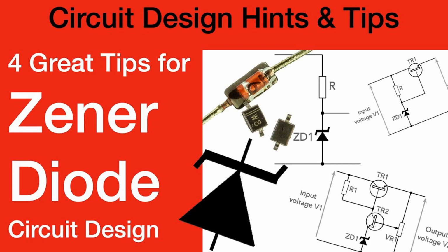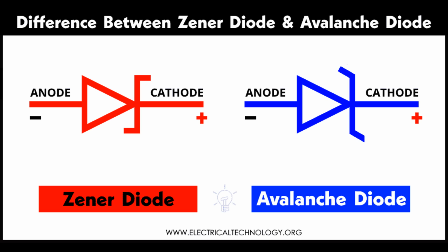Zener diodes come in various types, each designed for specific applications and performance characteristics. Here are the main types of Zener diodes. 1. Standard Zener diodes. Description: These are the most common type of Zener diodes used in general-purpose voltage regulation and protection applications. Characteristics: available in a wide range of Zener voltages, typically from 2V to 200V. Moderate power dissipation ratings, typically up to 1W. Suitable for general voltage regulation and protection tasks. Applications: voltage regulation and power supplies, overvoltage protection, and voltage reference circuits.